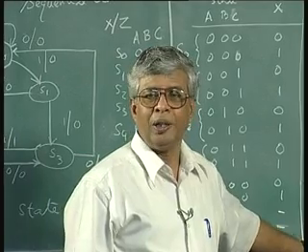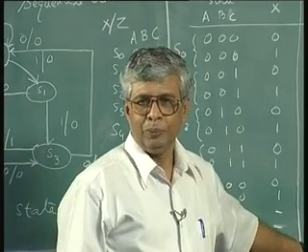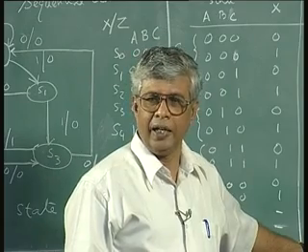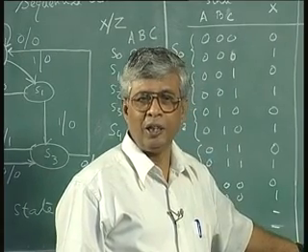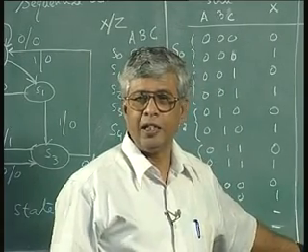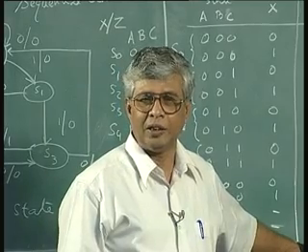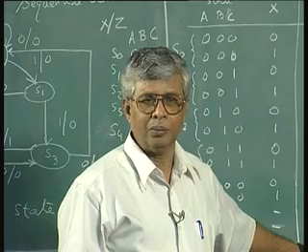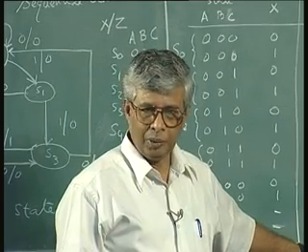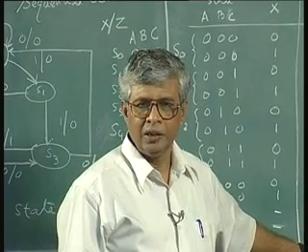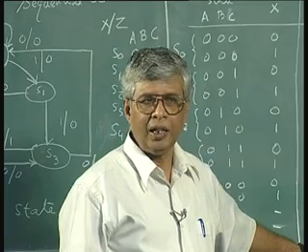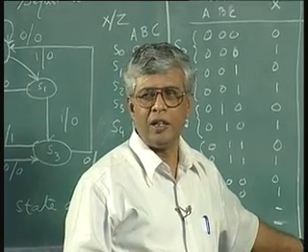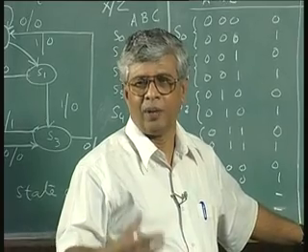Now, I am going to introduce multiplexers in the place of the combinational logic which we have earlier done using gates. Let us try to do a multiplexer based implementation. I will still need D flip flops because multiplexers can only give you the steering logic. Multiplexers are combinational building blocks, and a combinational block is only logic which controls the state transitions of the flip flops.